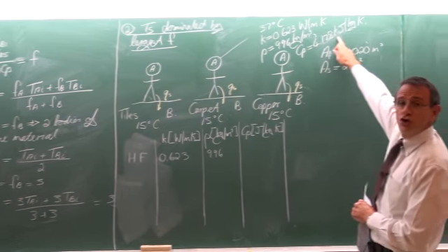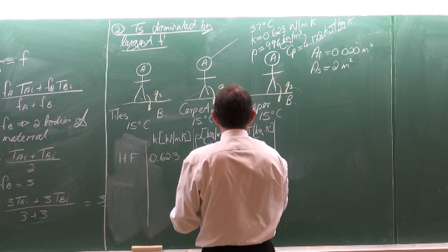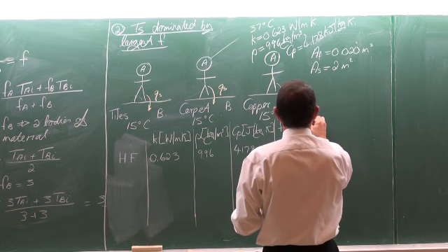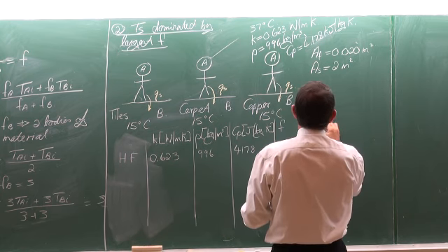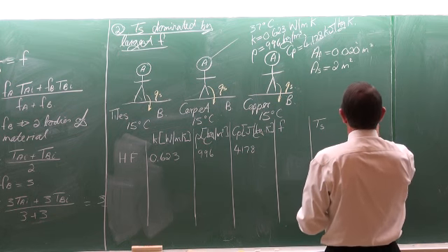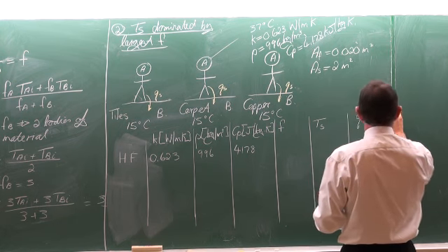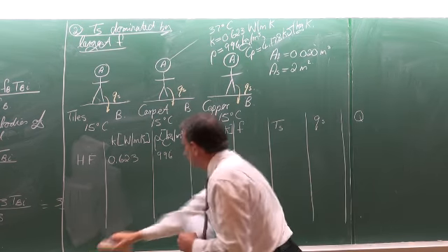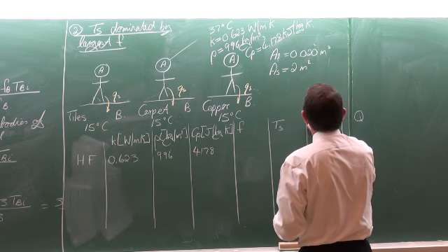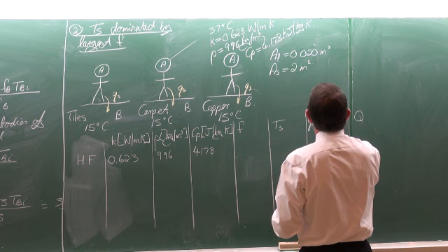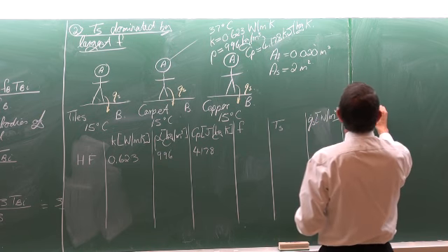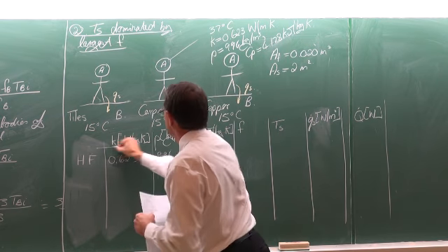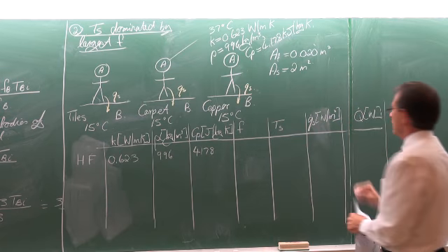Okay, that value is in kilojoules per kilogram Kelvin, so it is equal to 4178. And we're going to calculate the F value, the surface temperature, the heat flux, and the total heat transfer. The heat flux in watts per square meter and the total heat transfer rate in watts. So everything in one table.